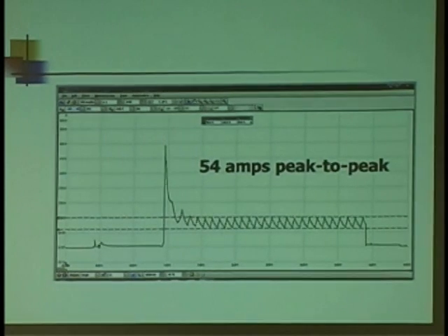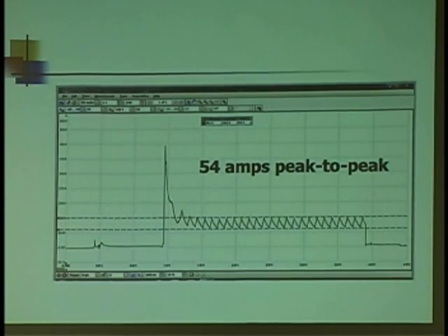One of the things I would first encourage you to look at is what is the peak-to-peak current? This one's almost 54 amps. That's pretty strong. If I didn't see that high a peak, if they were all nice and uniform but a lot closer in height, shorter if you will, then I would have a question about the actual total compression of the cylinders. You see what I'm saying? Relative to each other, they're fine. It doesn't mean that they're all at 100% of what they should be.